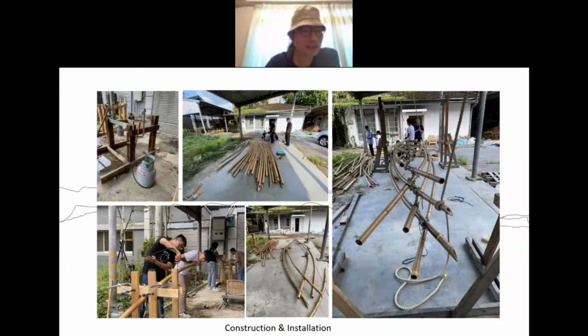We start with fire bending bamboo in the woodshop, which is in our university, National Taiwan University, about 200, 300 km away from the exhibition. The first thing we learned is that the purpose of bending is to loosen the fiber, but there's a thickness in bamboo. The skin itself is more or less water repellent. So we found out the most important step to make it successful is to make it fully soaked inside with water. What we do is sprinkle water on the bamboo and then cover it with canvas overnight. And so now the bamboo itself is soaked with water.